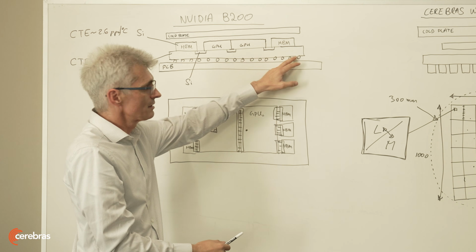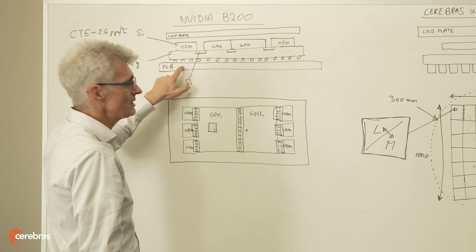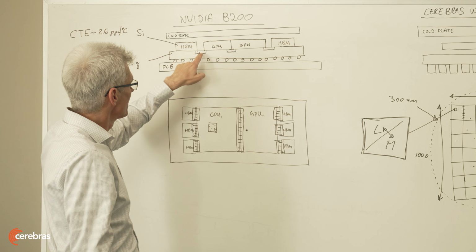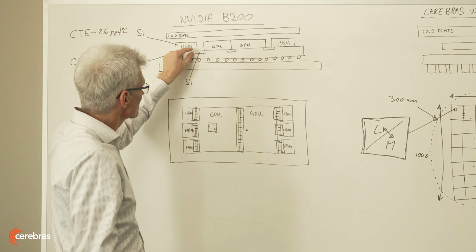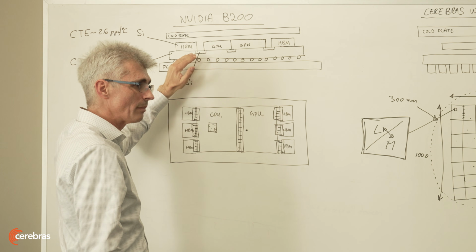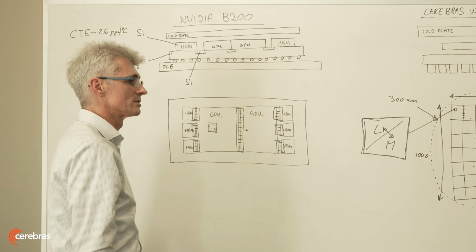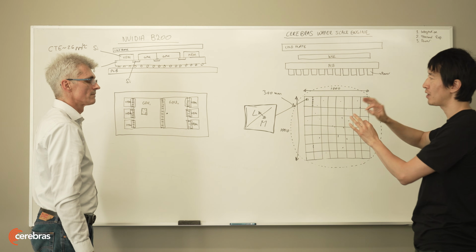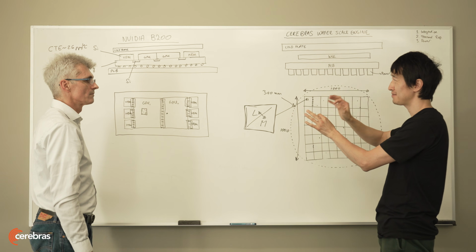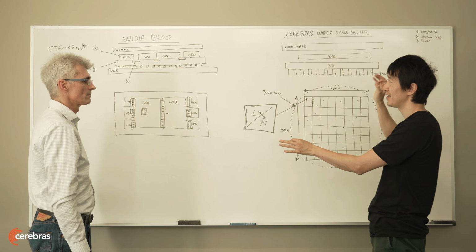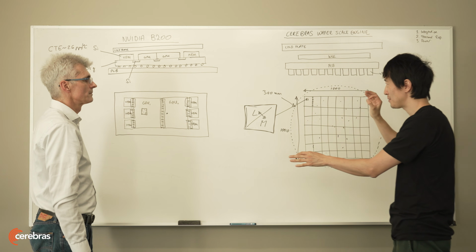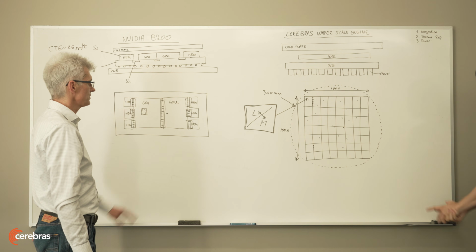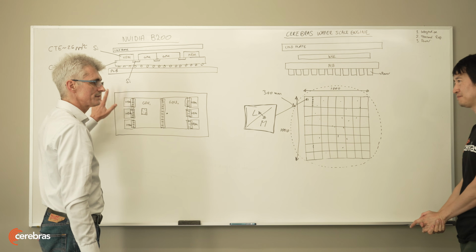You need the substrate, you need to solder this substrate to a PCB, you need these various dies to be soldered to the substrate, and you need the silicon bridge interposers to create the connectivity. So a lot of partners and assembly processes are involved. I see. If you call this the small chip approach, it looks like as we progress with AI and it requires more memory and more bandwidth, the small chip approach gets increasingly, almost exponentially, more complicated. The recipe gets more complicated, the tolerances are more demanding, and we stay as a single uniform chip with the same tolerances. Correct. So we completely alleviate all these challenges.